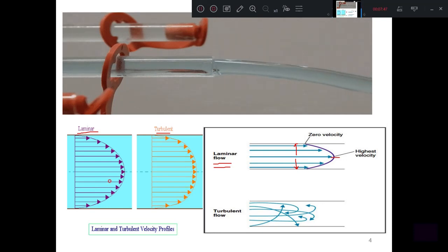So, as I mentioned, pipe losses in the piping system result from a number of system characteristics which include, among others, pipe friction, changes in direction of flow, obstruction in the flow path, and sudden or gradual changes in the cross section and shape of the flow path. So this is about what we call flow through pipes.